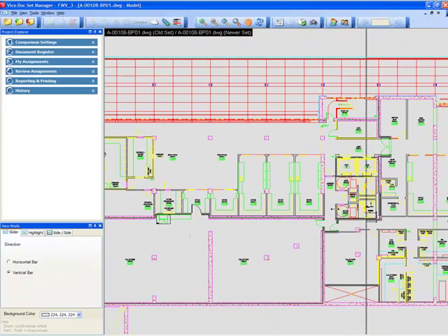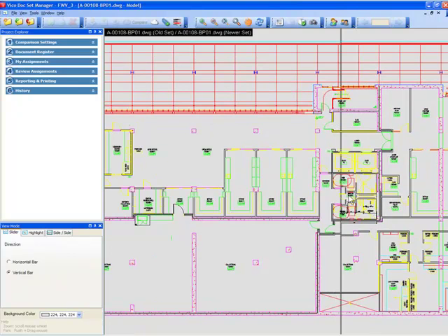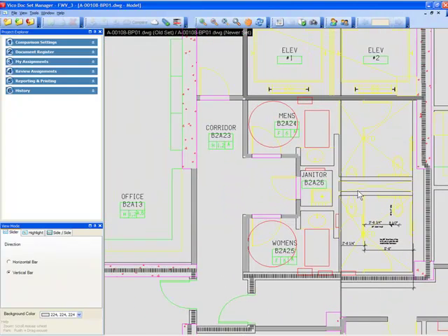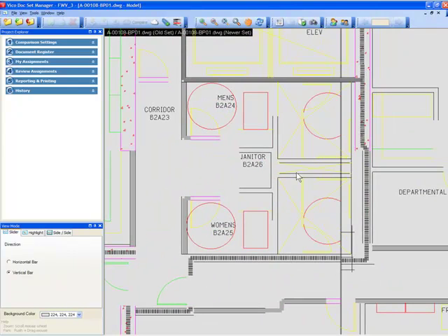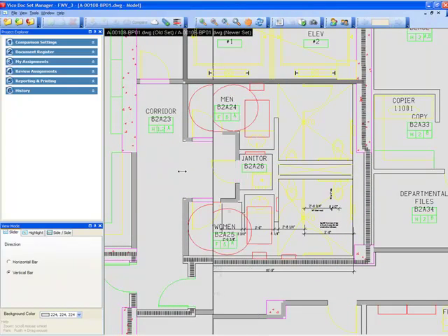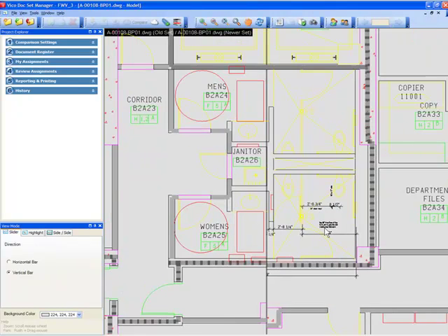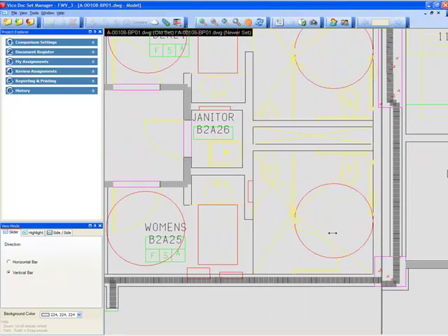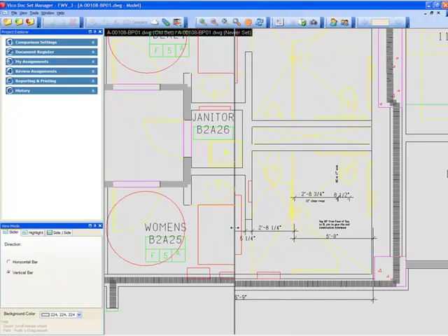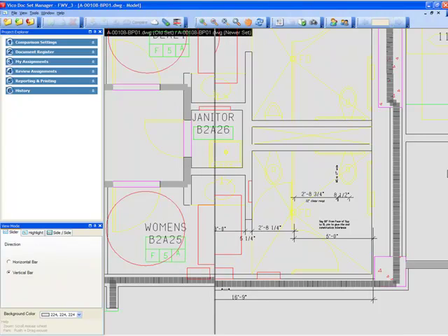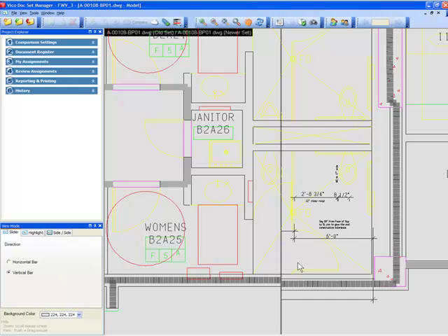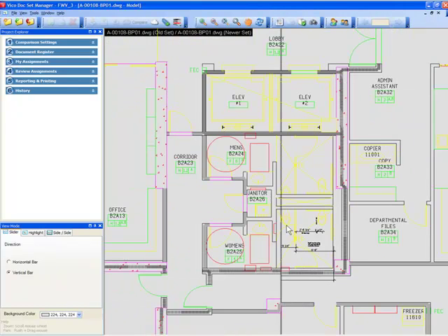I remember the bathroom had a lot of orange in it. If you look in here, I'm going to zoom up big on it here. Bring it to the middle. I'm going to sweep. You can see you just got something blinking at you. Well, that's a good sign something's changed. And if I want to make sure, I can see we got some ADA issues going on or something like that. The circle's changed, bathroom's been modified, we got some new dimensions and things. We can see the wall has been jogged a little bit, see how the lines don't meet up there. Got some new dimensions and so on. All right, I found that. Our DocSet manager found it for me.